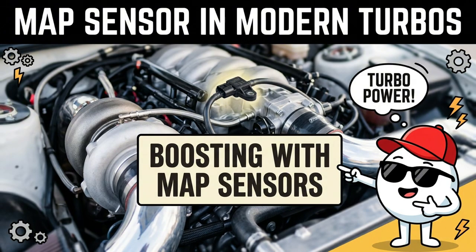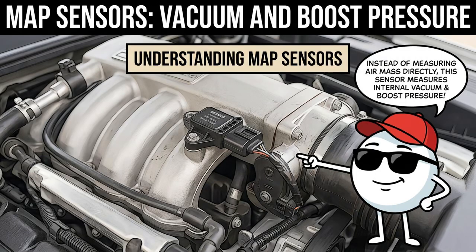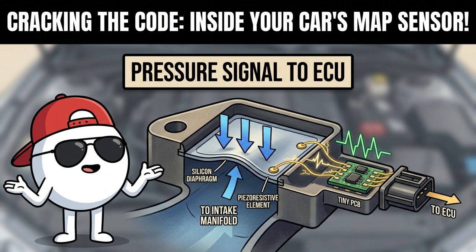Alternatively, many modern turbocharged or speed-density engines rely on a manifold absolute pressure sensor, or MAP sensor. Instead of measuring air mass directly with a hot wire, the MAP sensor mounts directly onto the intake manifold plenum to measure internal vacuum and positive boost pressure. Inside, a silicon piezoresistive diaphragm flexes under pressure changes, sending a corresponding voltage signal directly to the ECU.